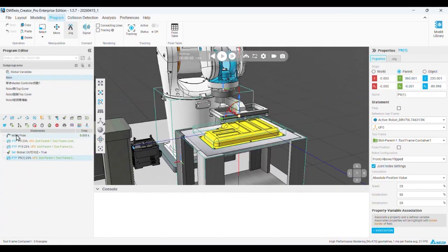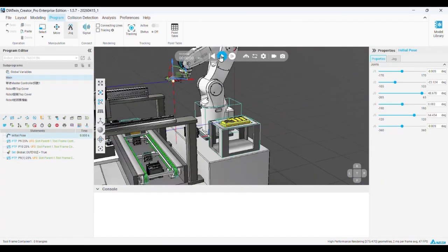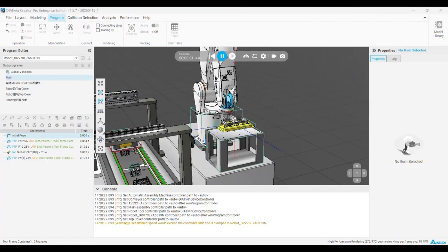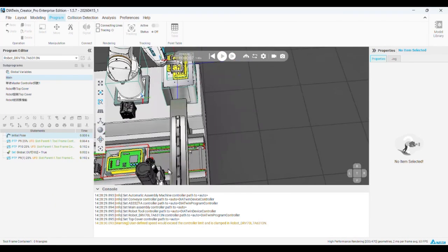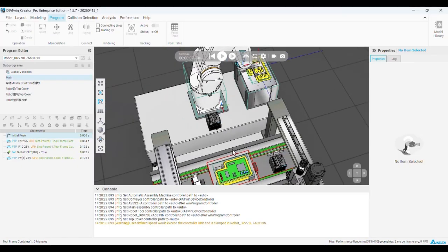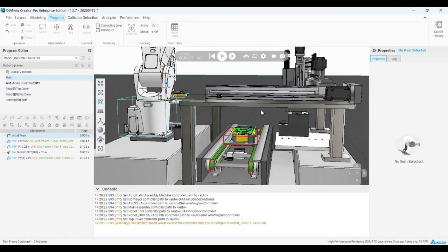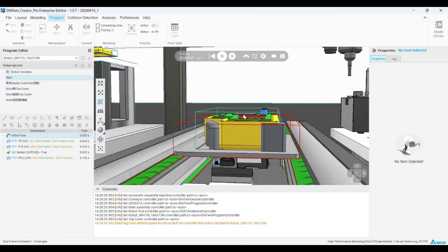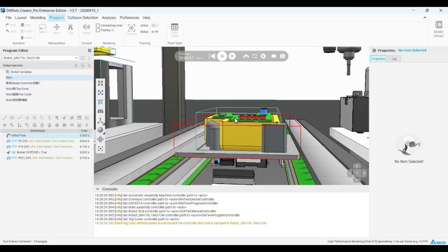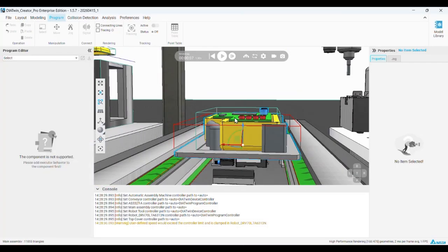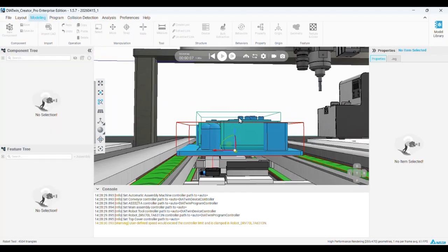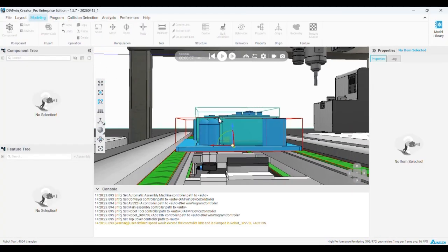Okay, so now we can select initial pose again. If we try simulation, now they will go pick and place. Picking. Okay, so I think after pick, now we can try to place. But here we can see maybe we need to fix something for this placing, right? Like this bounding box. If you have this bounding box, maybe you have to delete one because another one is too high. So there will be a collision.